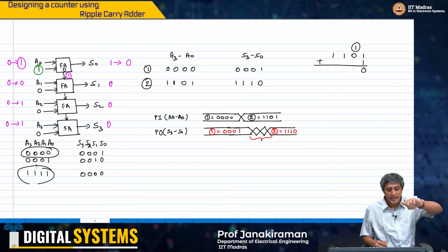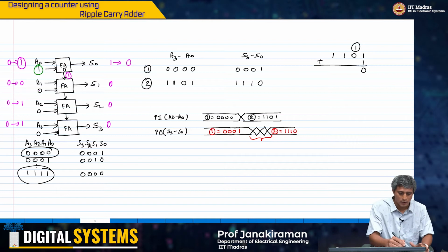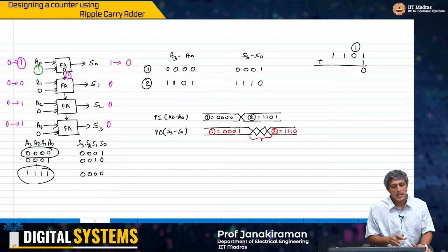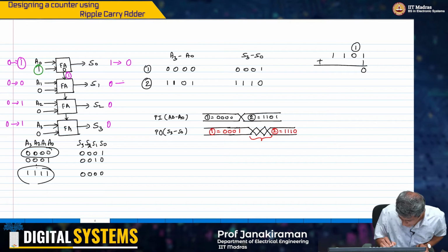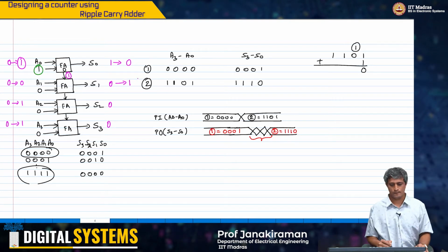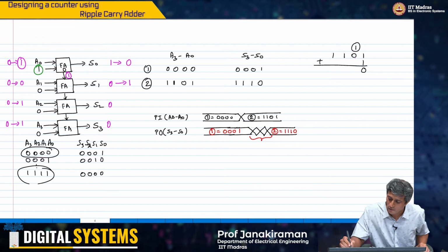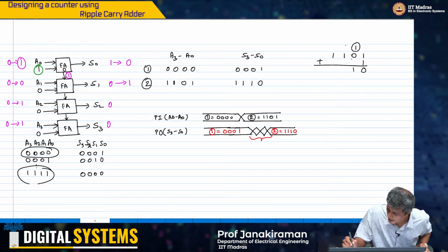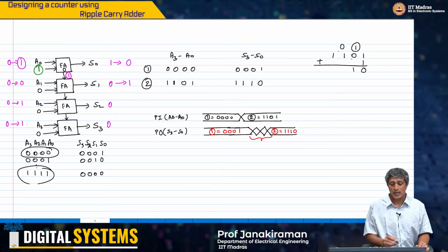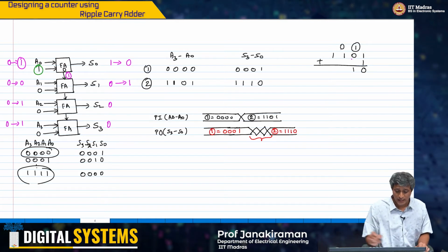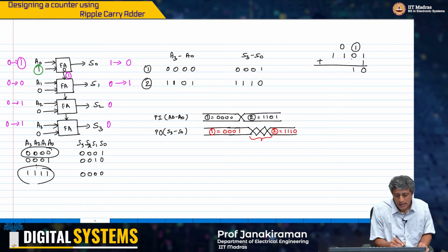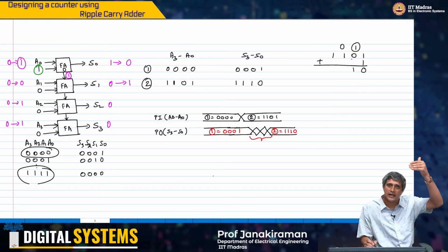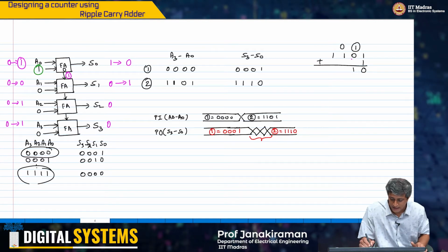So now the carry gets added with the input A1 equal to 0 and the other B1 equal to 0, that is already 0, and this will then become 1. Now I add 1 plus 0, I get 1 as the answer, there is no carry. And now if there is no carry, then actually A2 arrived at t equal to T1 itself, at this instant.